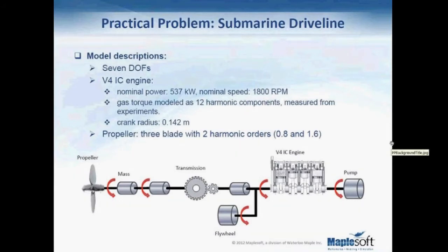I know the range of speed that the system is spinning, and I want to investigate why the system makes so much noise, or what the weakest parts of the system are, so that I can improve the design to prevent a system breakdown. This requires a complete vibration analysis for the driveline.